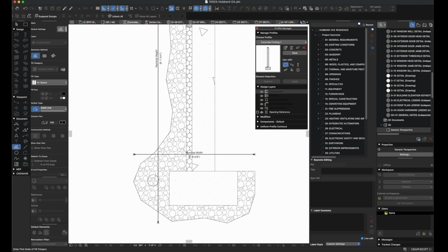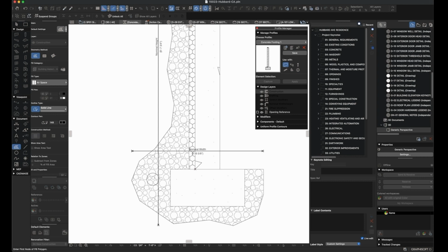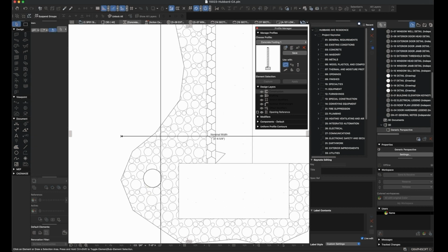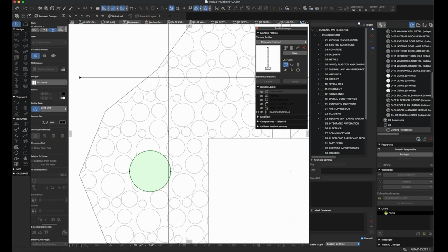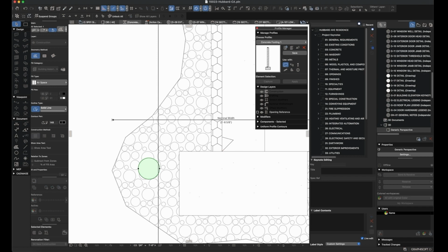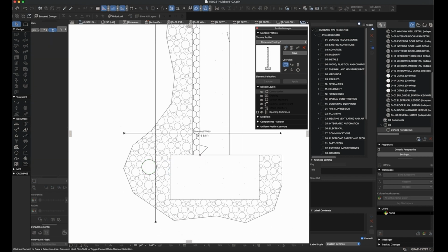Now, because we've already drawn the circle, we can use the magic wand tool. What we're going to do for the magic wand tool is hold the space bar. You can see the magic wand showing up. We're going to hover over the circle so that the fill region will follow the circle. Now we've got a filled region that's airspace, and it will be circular in shape.